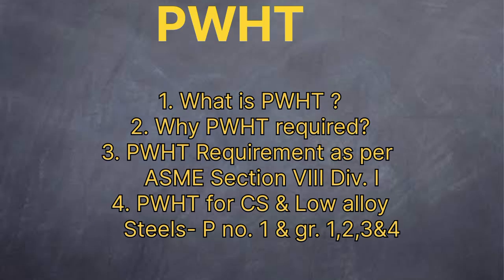Today I will discuss PWHT, which means post weld heat treatment. We cover four topics about post weld heat treatment. First, what is PWHT, why PWHT is required, PWHT requirements as per ASME Section 8 Division 1, and PWHT for CS and low alloy steel P number 1 grade 1, 2, 3, 4.